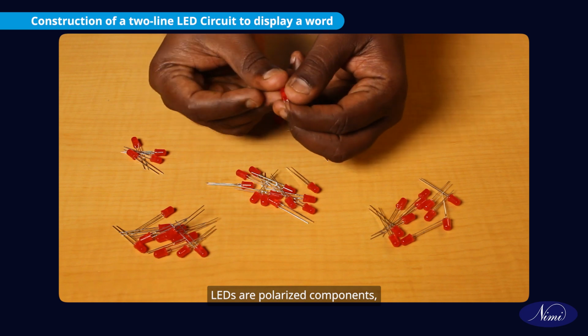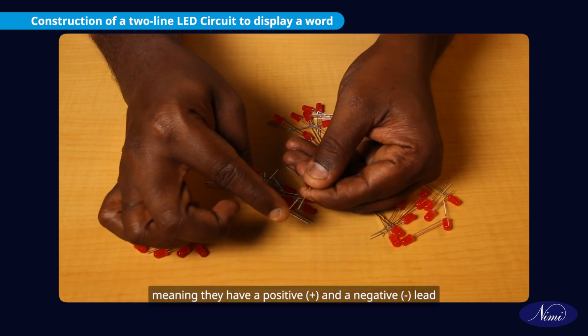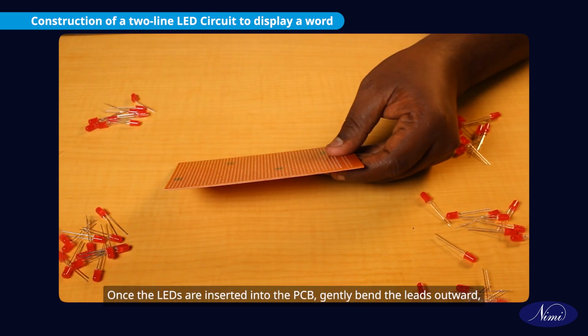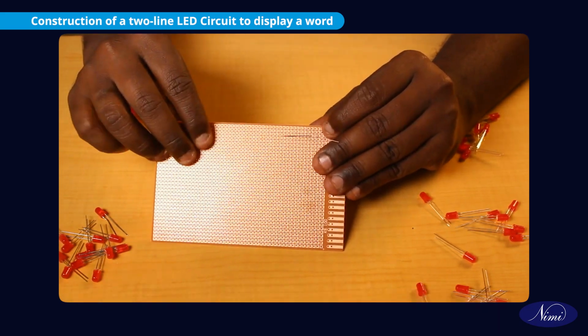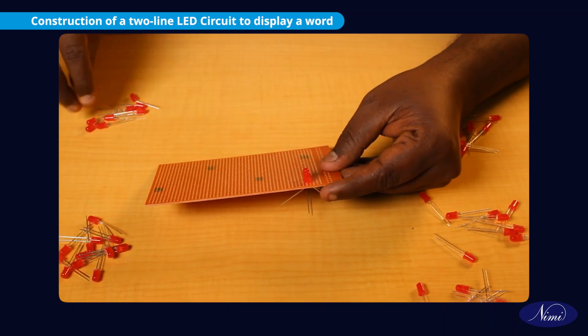LEDs are polarized components, meaning they have a positive and a negative lead. The longer lead is typically the positive anode and the shorter lead or flat side of the LED's plastic body is usually the negative cathode. Once the LEDs are inserted into the PCB, gently bend the leads outward. This prevents the LEDs from falling out during soldering.